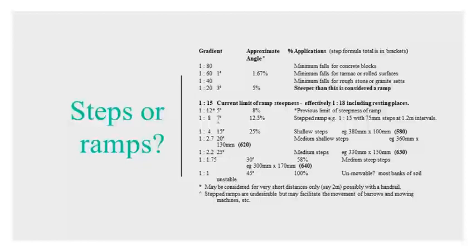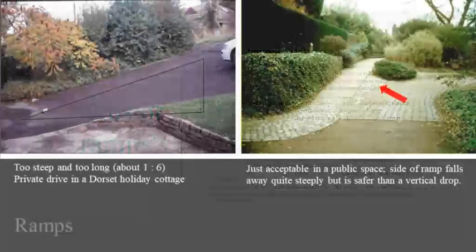The table demonstrates that with shallow falls, which apply on pavings and ramps, the most practical method of specifying the slope is to give a proportion, i.e. 1 in 60, rather than quoting degrees or percentages. More discussion of paving slopes or gradients is found in the seminar on drainage.